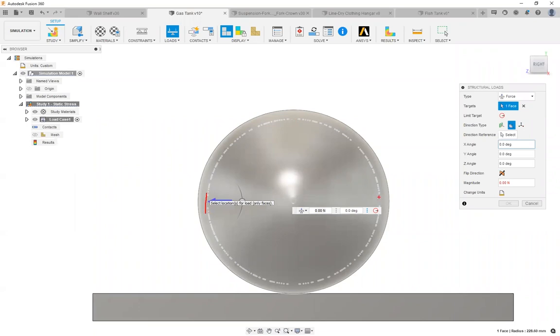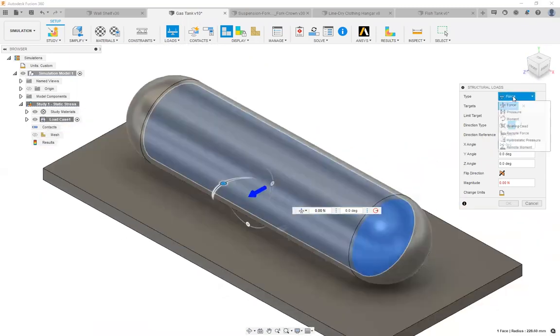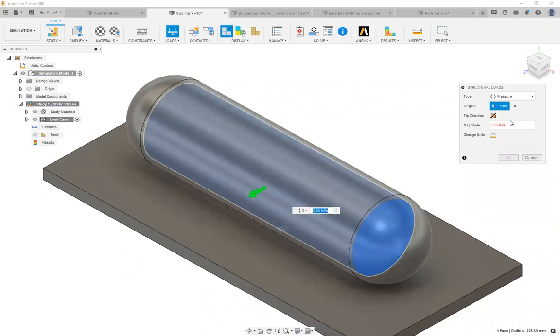But this surface over here, we actually want it to point normal to that surface, whereas it's actually pointing this way as well. It's also pulling the top one going here, as opposed to going somewhere like that. And the bottom surface is going left as well. So everything is going left where we want it to go normal to, or outwards in this direction from the center. So that's why you don't want to use force in this scenario. And that's why we would want to rather use pressure.